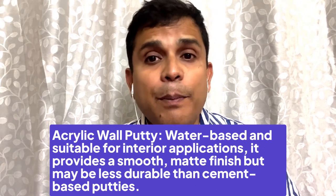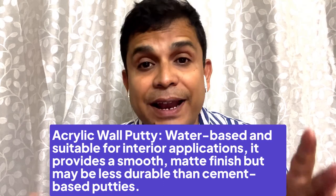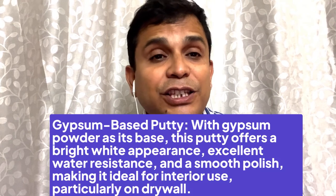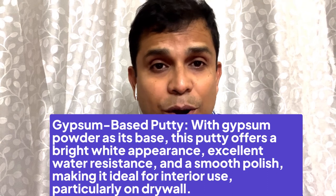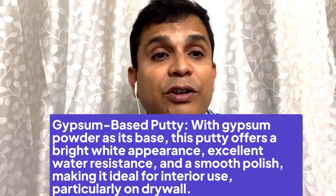So depending upon the requirement and area of use, we can choose either the white cement base or the acrylic base, and another one is the gypsum base, with gypsum powder as its base. In acrylic, the acrylic is the base. In white cement, the white cement is the base. The gypsum based putty offers a bright white appearance, excellent water resistance, and a smooth polish finish, and is ideal for interiors, particularly on drywall. So these are the three different types of wall putty we are using.